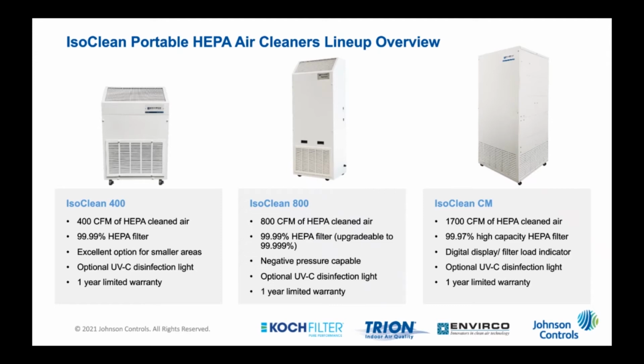So this unit can have a duct affixed to it, and the HEPA cleaned air can be ducted out of the space. And when you do that, it puts the space itself under a negative pressure. If you're not familiar with what that means, just think of it this way. If you were to crack open the door, you would feel air from the hallway rushing into the room. And that is because the room is under a negative pressure.